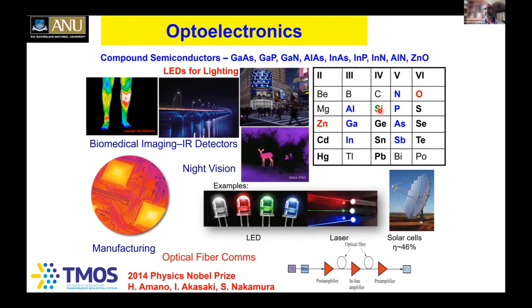So you need direct band gap semiconductors. That way we end up using group III-V semiconductors such as gallium arsenide, gallium phosphide, gallium nitride, gallium antimonide, and combinations of these materials. The majority of these compounds are also direct band gap semiconductors. They have different band gaps, the energy difference between the bottom of the conduction band and the top of the valence band.